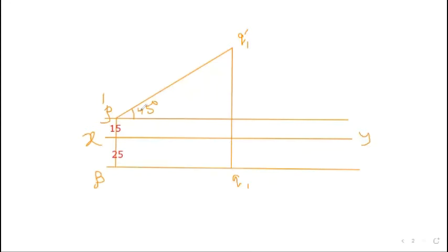So this is the projection of the line 45 degree with the HP. Now the problem is the line PQ 30 degree with the VP. In the previous problem we saw 45 degree, so what will be the projection here? This is 30 degree to the VP. At the top view we get the actual dimension, so first we draw the top view. Here draw a 30 degree line.